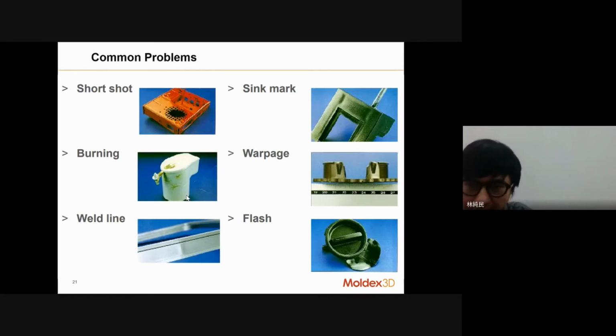So you need to think about everything from the part design and mold design to the material selection. All the factors will affect this, because, just like I mentioned, what's the main reason that causes warpage? Because the different parts take different times to cool down. Then after cooling down, of course there is deformation. Deformation at different times will pull each other, so it will cause warpage.